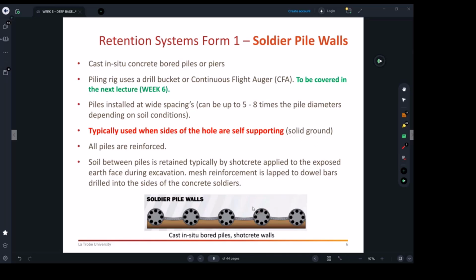But why? Because remember, who's really going to guide you to know which one to use? It will be documented on the engineering drawings, but before that, the geotechnical engineer, the soil engineer, will give you a report telling you this is what you can do. The way it works is this soil, the brown color soil here, if the soil engineer found it's got a mechanism to bridge over, because remember, this is built at a later stage. Day one, we're going to build the piles. Then we're going to build a pile cap on top. Then later on, we're going to build the thin shotcrete walls.